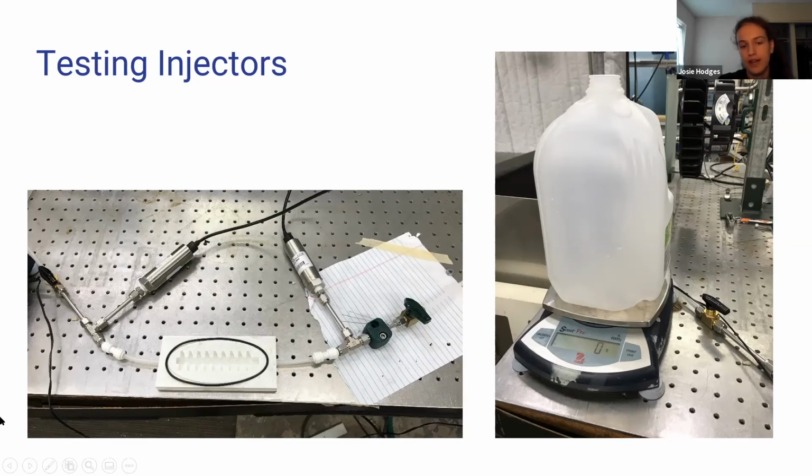And then these tubes are connected to a pressure inducer. This measures the pressure at the beginning of the injector and the pressure of the water after the fluid has passed through the injector. To take these readings, I would run the pressure through the injector, and I had LabVIEW code set up that told me the pressure at the beginning of the injector and the end, and I was able to calculate the pressure drop from that. I think this is set up for forward flow. When I needed to measure backflow, I would just unplug the injector, twist it around, and plug the tubes back in, and I could measure for both sides.